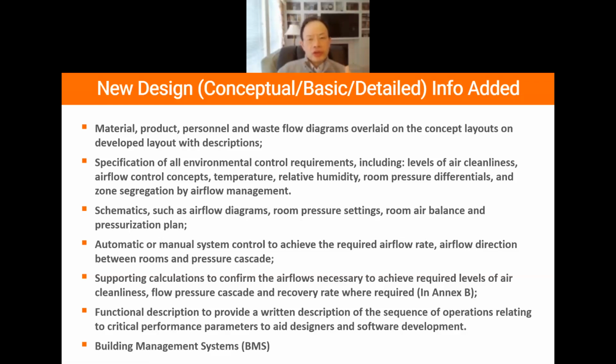So you have a full flow diagram, or what we call traffic passage, for material, product, personnel, and waste. The design engineer needs to check that these four flows do not conflict with each other or cause additional concern for contamination control.